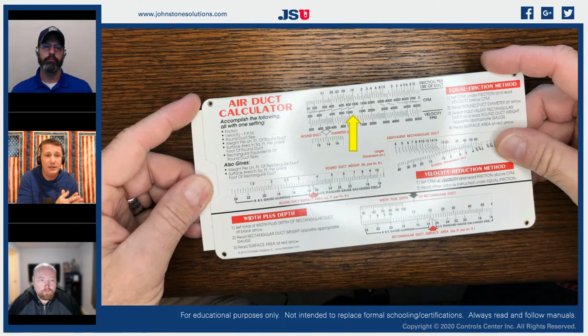If we go back to the fundamentals of static pressure and understanding what we're reading, do we all remember how we originally read static pressure? We took a 1-inch glass tube, put it in a U-bend, and we put water in it. Plain water. Distilled, hopefully, but a lot of times it's tap water. And we hooked up a hose on each side of that, right? That was our manometer. That's what told us how much pressure we had on our ductwork.